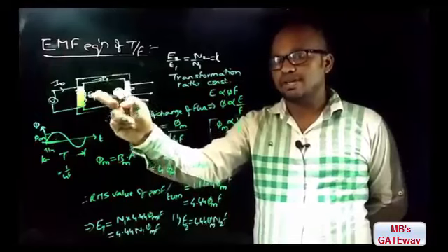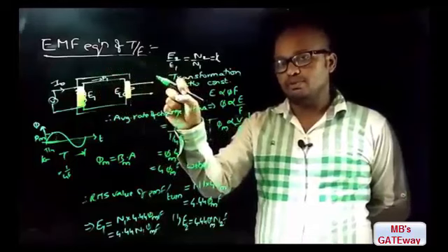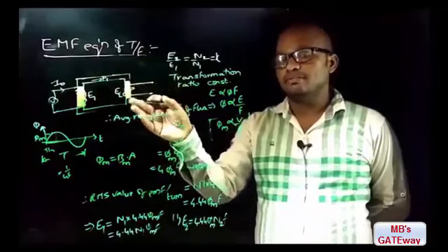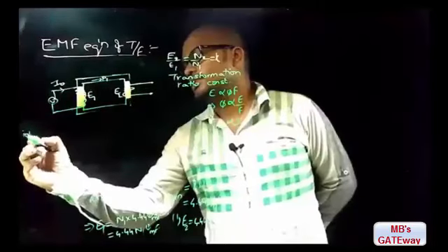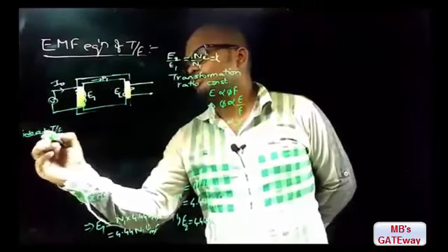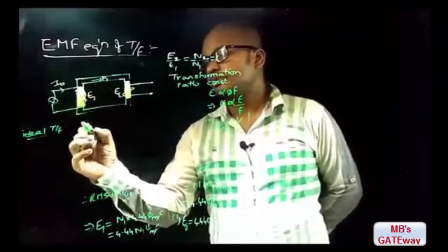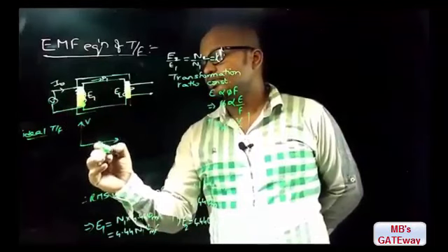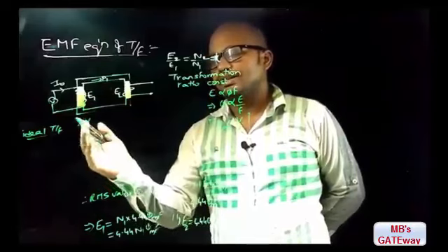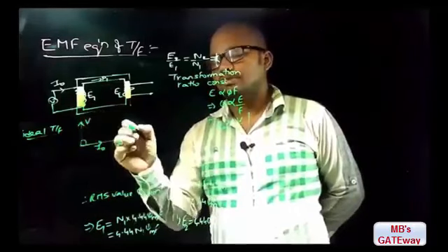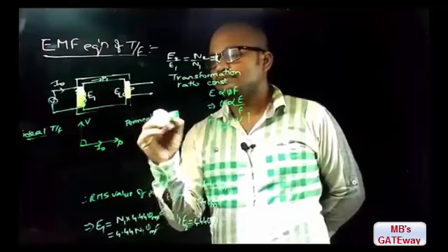If magnetic saturation happens, the transformer will drag more magnetizing current from the input. If more magnetizing current, then power factor will decrease. How it will decrease, now let's analyze that. Let us consider an ideal transformer. In this case, if you observe, the primary winding is of inductive nature, therefore the no load primary current and flux will be exactly 90 degrees lagging with the input voltage. And this is the case if we assume permeability is constant.